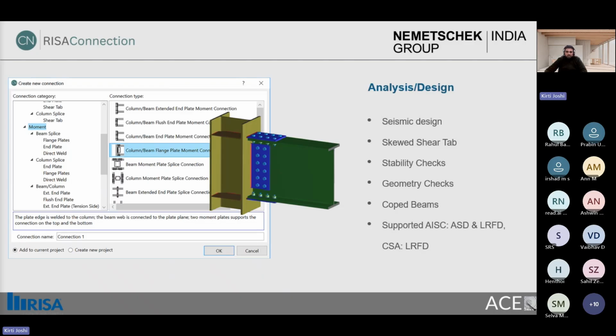Like I mentioned, users have the option to design and optimize steel members, and also utilize practical seismic connections designed for moment and braced frames according to AISC 341 and 358, and can also analyze non-concentric connections such as the diagonal brace.